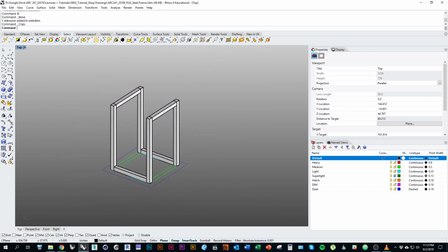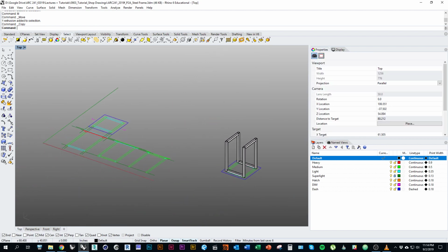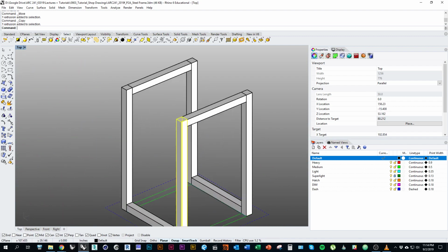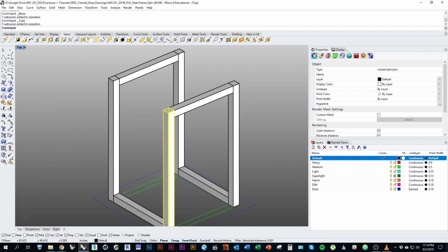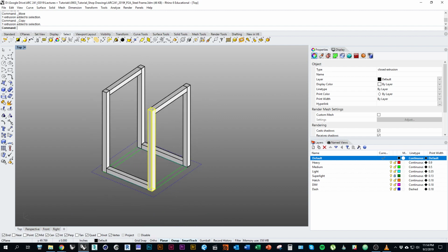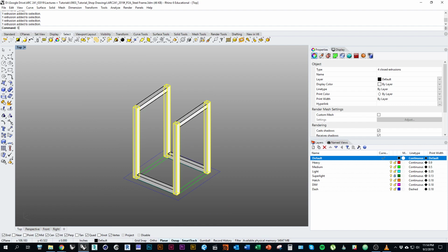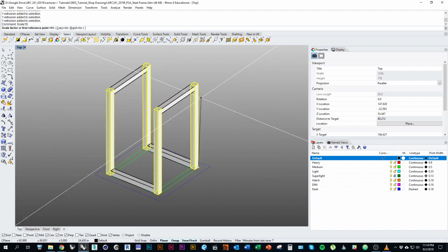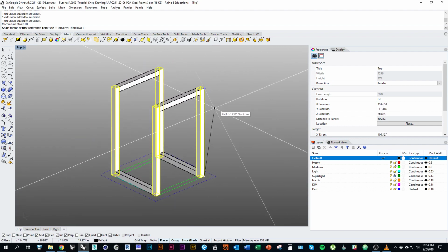Okay, so that's the stool frame. The last thing I want to do is, if you remember when we drew the elevations, we added a little cap plate on all the uprights at 3/16 of an inch, just to close the top edge of our tube frame. So what I'm going to do is scale these back a little bit. I'm going to select all four of my uprights and type in scale 1D, one dimension. What that allows me to do is scale something along a line, essentially.